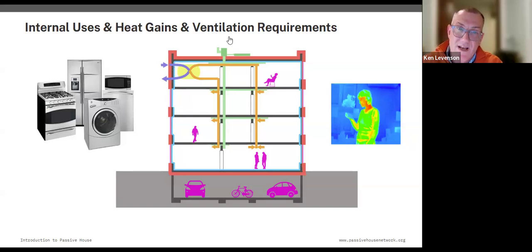If your unit's outside and it's coming in, the ducts between the unit and the thermal enclosure need to be well insulated to do that. Within the conditioned space itself, the ducts don't need to be insulated. What affects the efficiency is if the ERV, HRV is a long distance away from the enclosure, so you've got a lot of duct run that's effectively outside.